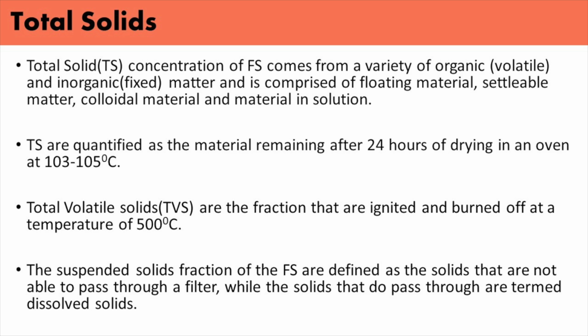The total solids values are important as they are used to design and dimension fecal sludge treatment technologies such as planted and unplanted drying beds. The suspended solid fraction of fecal sludge is defined as solids that are not able to pass through a filter, while the solids that do pass through are termed dissolved solids.